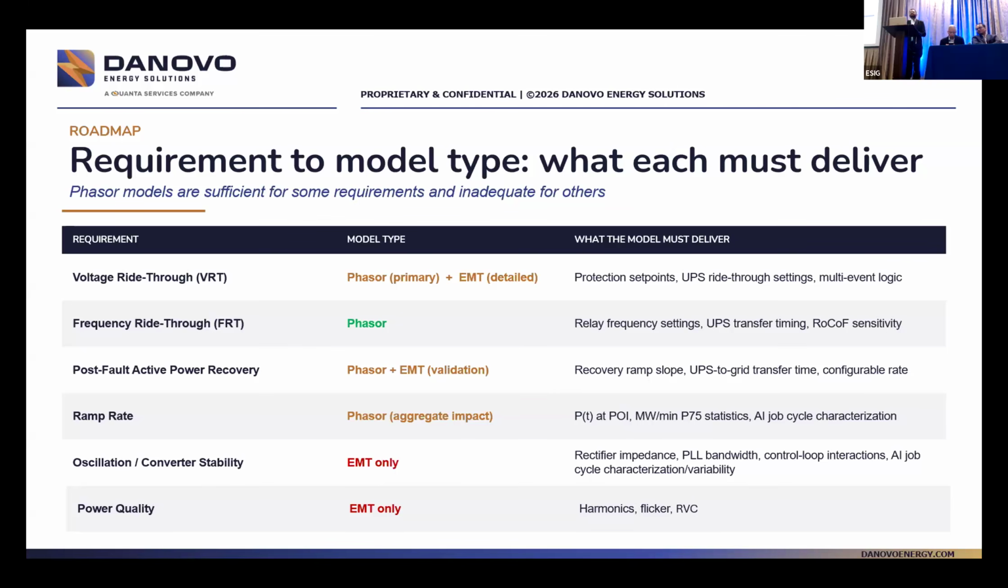Now, if you have a battery that is going to suddenly show up, right, and the load is still connected, but then the battery is kind of overtaking and showing up as a grid for you, that battery is going to need to perform at a different kind of ramp rate than how you would typically expect a grid-connected PSU, which reduces its power output proportional to the voltage, to behave. Different considerations, right? And all the NERC papers are going to go into all of that.